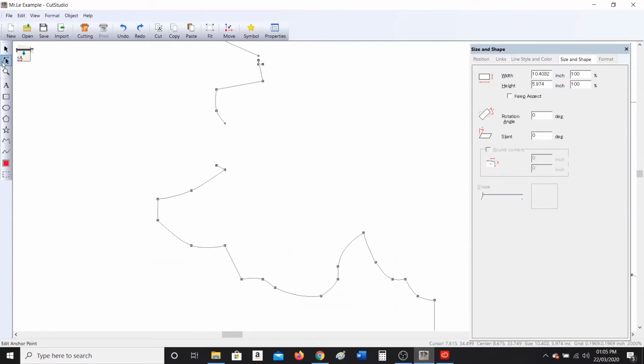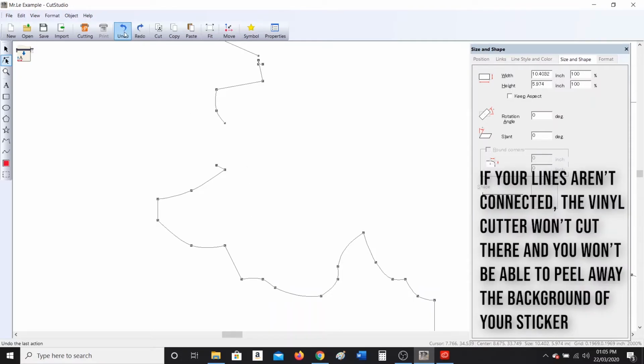So I'm going to go to edit tool. If you click and highlight a point, so it's blue squared, and then you right click on it, you'll get this menu here. Honestly, at the end of the day, you guys, if you use common sense and do a little bit of self-exploration yourself, you'll figure out what most of these functions do. For instance, if I go to snap to nearest point, what it's going to do is connect the point that I didn't have connected before. Just go undo there, alright?